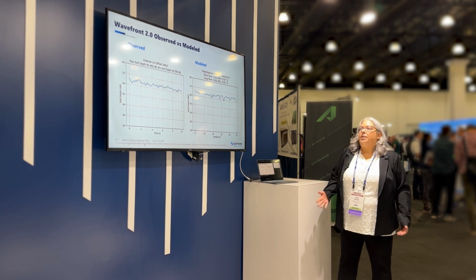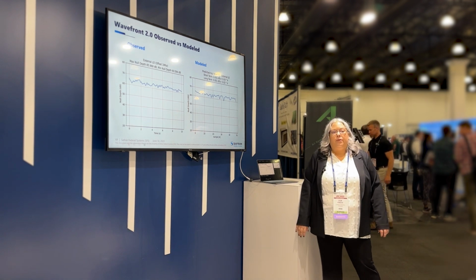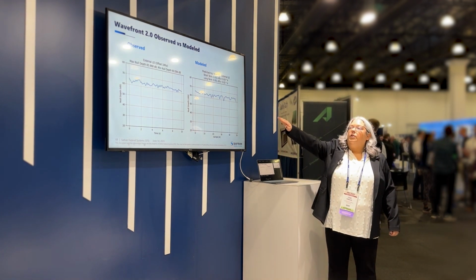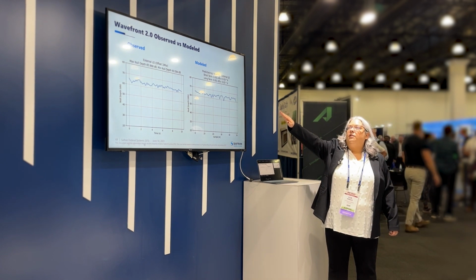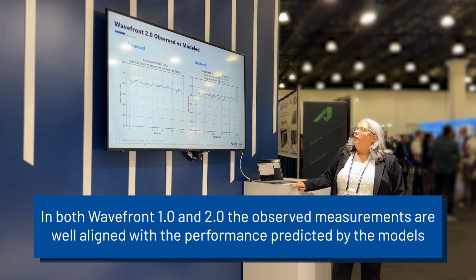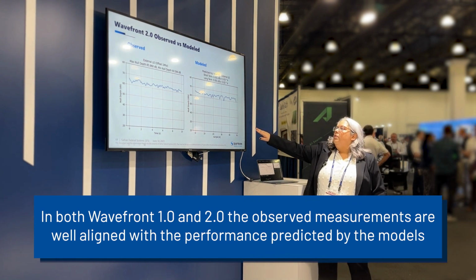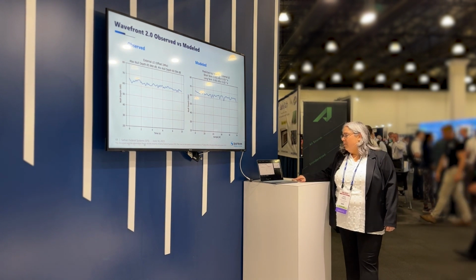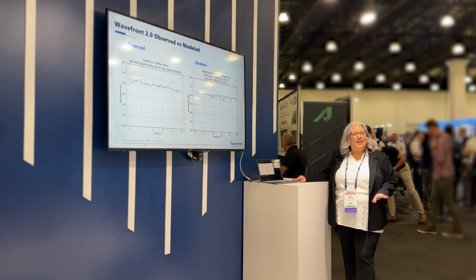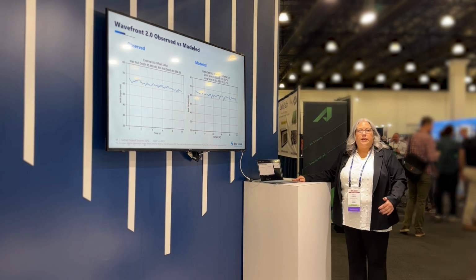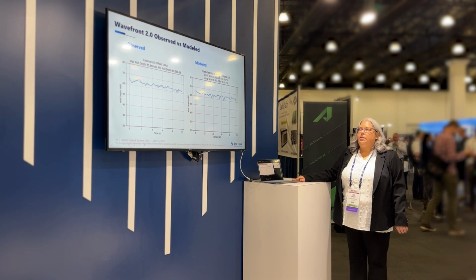We can do the same thing with the improvements that we've made in Wavefront 2.0 and see that the null depth has gone over 60. The next null depth there was 65, almost 66 dB, and it also aligns very well with the model. So when we're playing with this stuff and seeing how it affects the model, we're fairly confident that that's going to translate into the system, and we can measure it to verify.